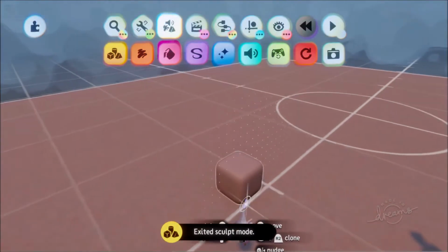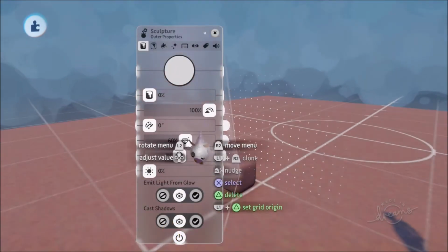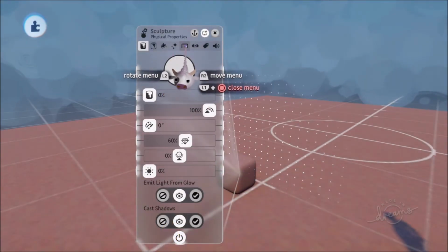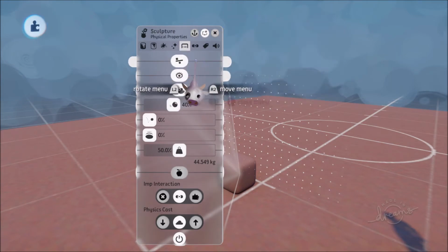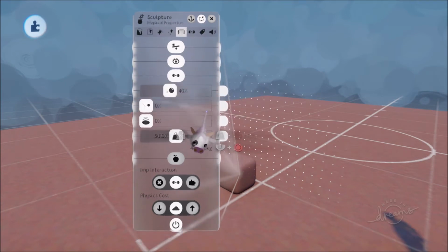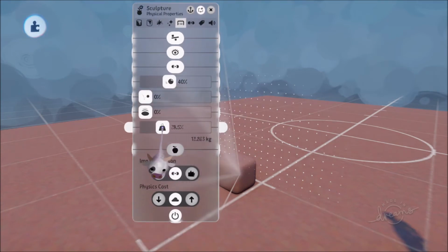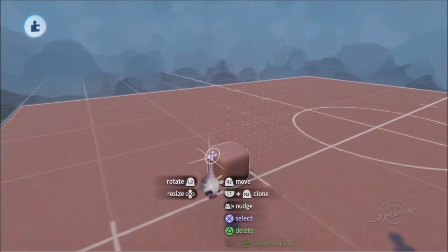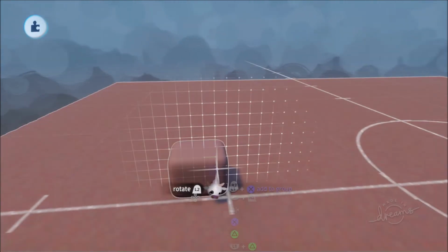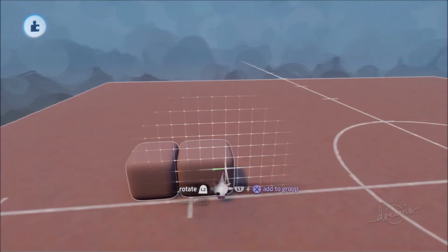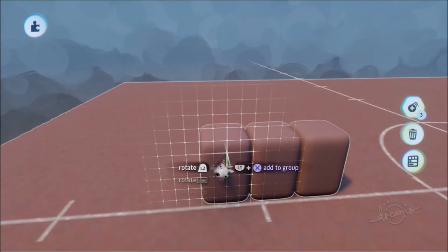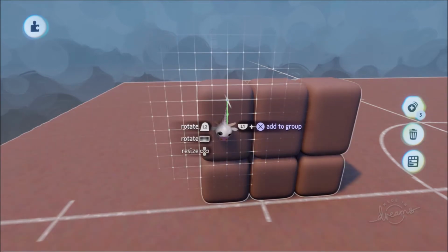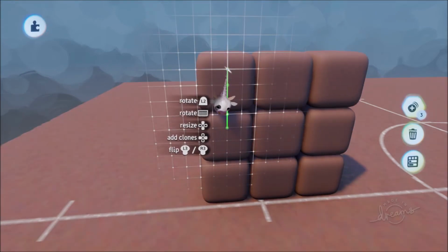Right? Then you're going to want to edit this chap. You're going to want to go to physical properties, then you'll turn it on movable. So you'll activate movable, but that's not all, because you're also going to want to reduce its density. So that basically makes it lighter and easier to move around, and it'll make that force push all that more impressive. You can keep it with a heavier weight, but then you might have to increase the good old force of your Force Applier. But I thought we'd keep it nice and light and breezy.